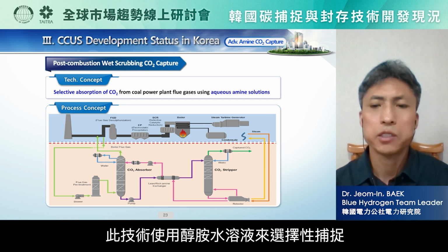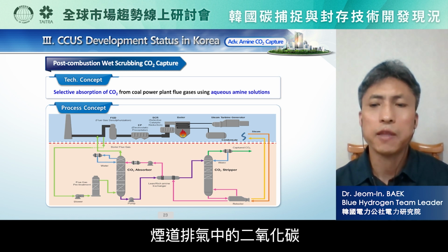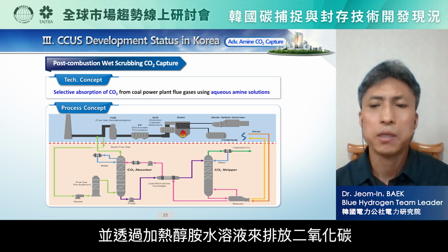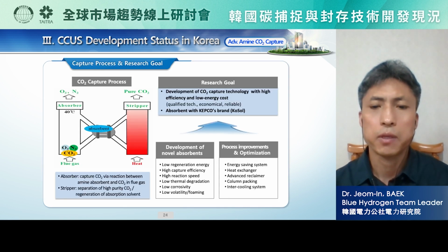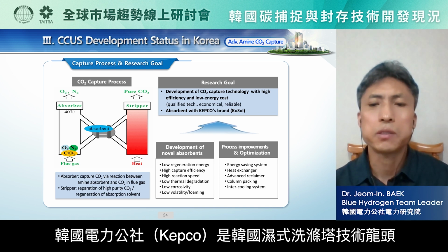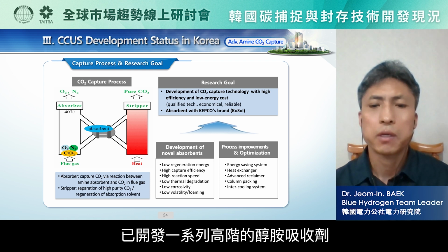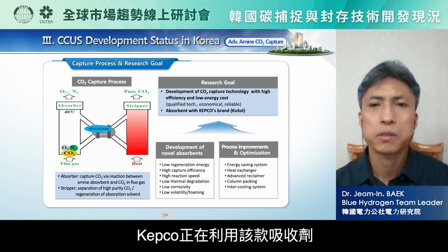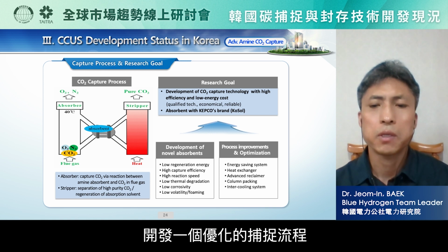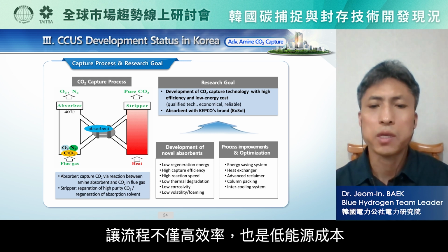In this technology, CO2 in the flue gases is selectively captured in the aqueous amine solutions and emitted by heating the solution with steam. KECO is leading waste scrubbing capture technology development in Korea. KECO has developed a series of advanced amine absorbent. With this absorbent, KECO is developing an optimized capture process with high efficiency and low energy cost.